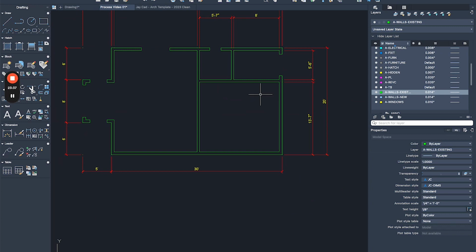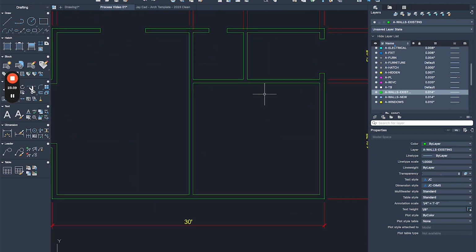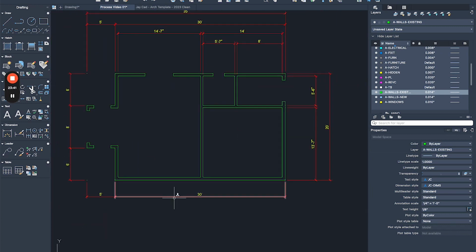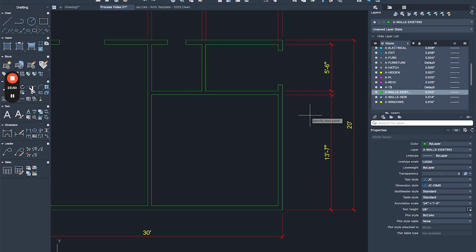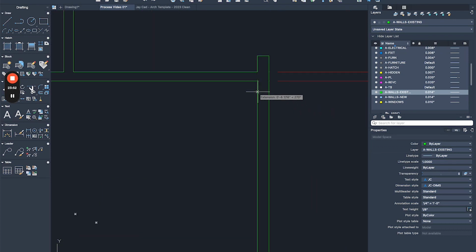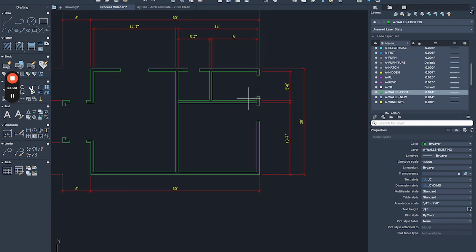So this is good. So now for the bedroom, so I'm kind of working on the windows now, and then we'll start working on the interior openings. Before we go, let's do a quick save. It's a lot of progress at this point, so I'm happy with it. So I'm gonna go from this corner, I'm gonna do 6 inches, and then I'm gonna offset this by, let's do 3 feet. Okay, I'm gonna do like short windows.